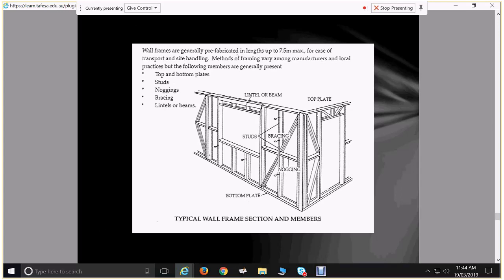So your bracing can be designed the same, but what does end up being different with your manufactured steel frames is that quite often it's all designed by a computer with design software and all cut by machine. It's very easy to do these things where you've got diagonal elements included within your frames. And steel to steel fixing is really easy with tech screws, so self-tapping metal screws that just fix everything really well. So you can have a little bit more complexity happening in your steel frames, and a lot more accuracy in the manufacturing and the cutting of them as well. So that's going to make a bit of a difference.